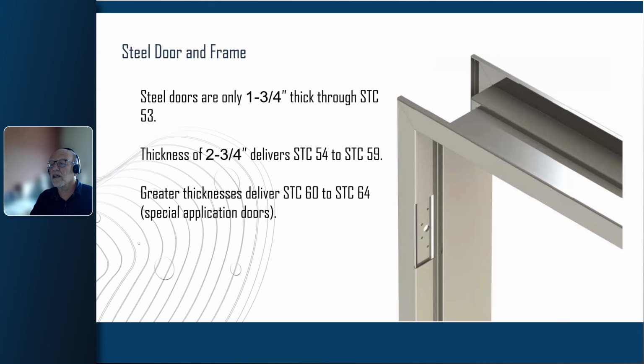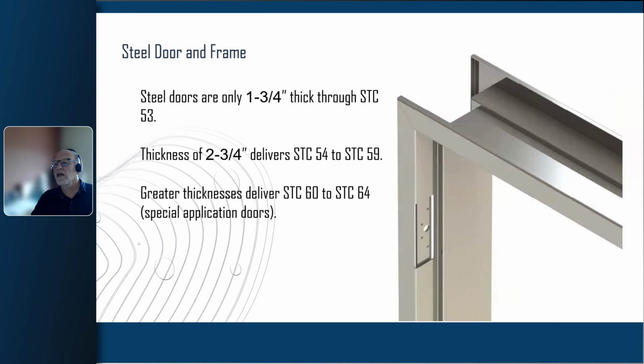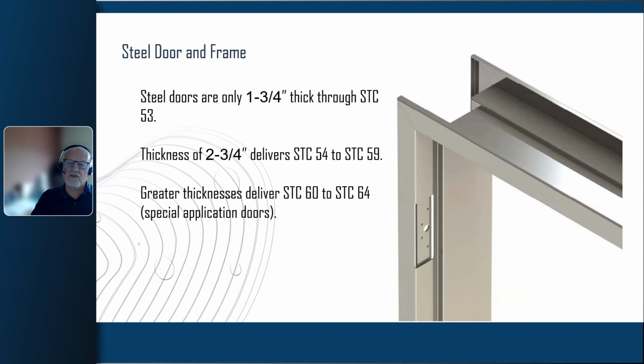And I talked at the beginning about the size of doors, so up to STC 53. And this is going to change from manufacturer to manufacturer. So I don't want you to think that all STC 53 doors are 1 3/4 inch and that they all have to go to 2 3/4 afterwards. Different manufacturers are going to have different requirements.